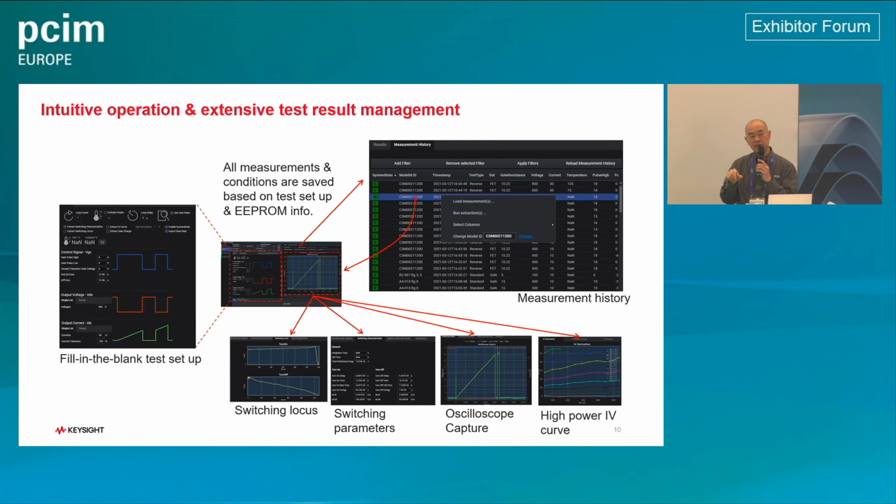So you can get a very low voltage with a very high current, or a very high voltage but very small current. You cannot get the characteristics where you have both high voltage and high current, right? But double pulse test is very convenient and good because you have a very fast pulse, so energy doesn't matter.